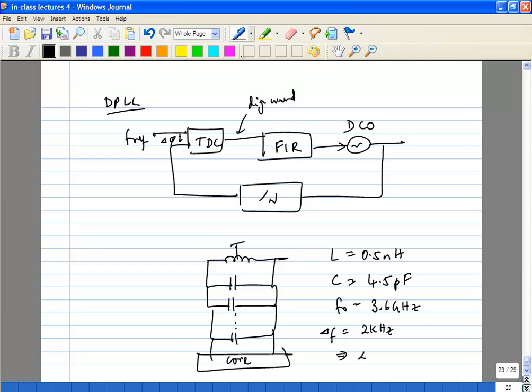Delta C will turn out to be approximately 5 attofarads, which is 5e minus 18. Believe me, these kinds of resolution capacitances are possible. In the latest processes, this kind of capacitance is definitely possible. What people generally do is rely on fringing capacitance. Remember that these parasitic capacitances are usually very low, and you try to keep them low. So people create the capacitances using fringing capacitance.